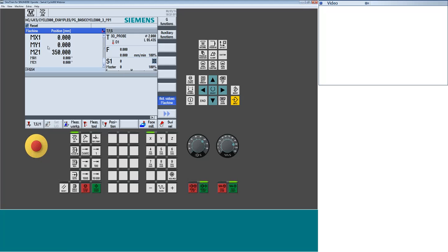So whether your machine tool has incremental encoders or absolute encoders, absolute being you don't actually have to home or grid or reference your machine in the morning, it still always has a machine 0. And that was where that machine was first commissioned from. So that's where all these numbers are coming from. That's the machine value. The work is our first real shift. I'm now staging a 0 somewhere on the table of the machine because that's where my part program is relative to. So I always want to be displaying work whenever I'm setting up a job.